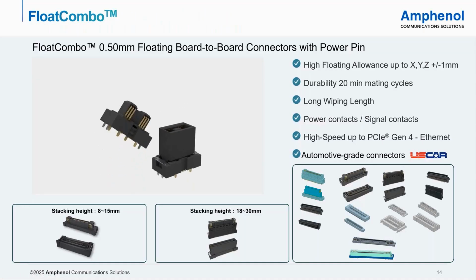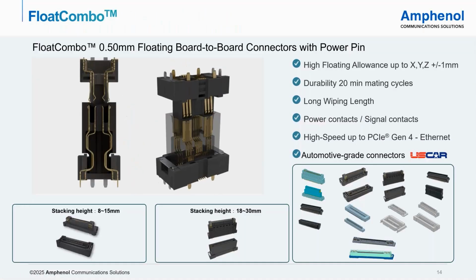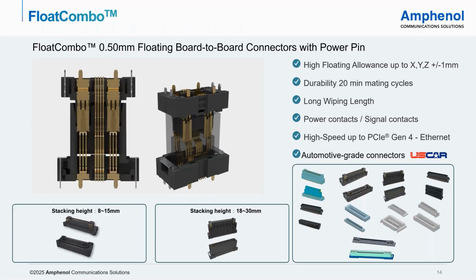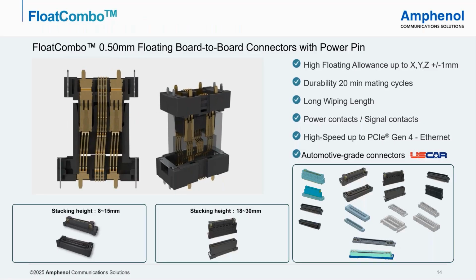Floating board to board. So to connect two PCB boards, there can be a misalignment, and if the connector is not guided between the two PCB boards, we have to be careful to have no stress on the solder tails. For this, we have a floating board to board.